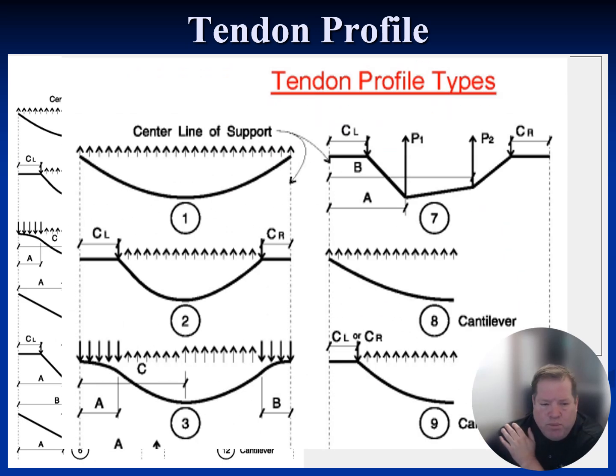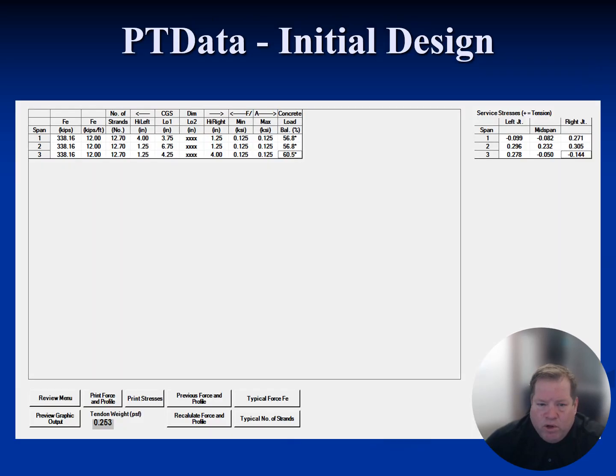So we're going to assume the tendon is flat over the extent of the column, then basically you have a simple parabola and then flat again. Probably, to be technically as accurate as you want to be, 3 is probably similar to how it's built. We typically use 2 for two-way slabs because they're relatively thin, but either one of those would work well for your purposes.